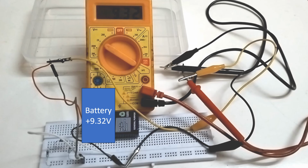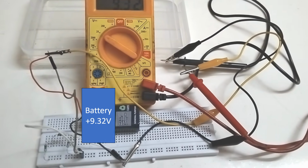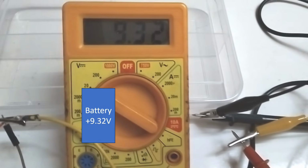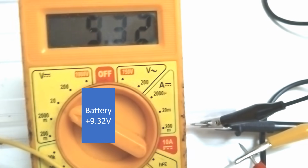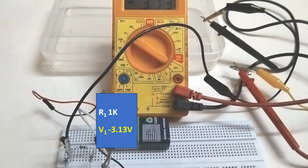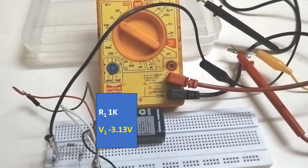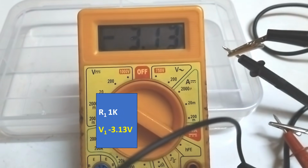Now we will use a simple circuit with 3 resistors and a battery to check Kirchhoff's voltage law. Three 1 kilo ohm resistors have been connected in series to a 9 volt power supply, that is exactly measuring plus 9.32 volts, and we will see what happens at each resistor level. This is the drop of voltage across the first 1 kilo ohm resistor. You can see that it is minus 3.13 volts.